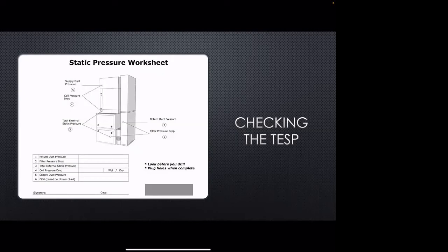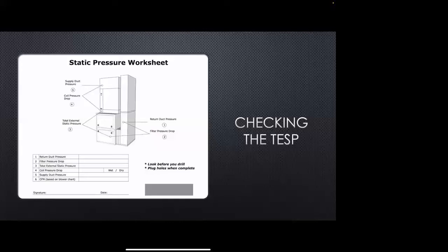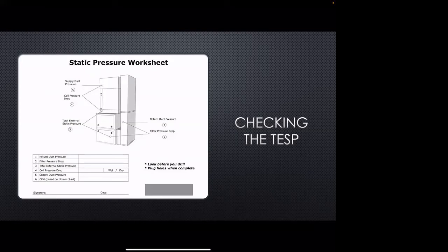Okay. So what they've done to combat that is they started actually putting their pressure drop at a certain CFM on their filter. So it's printed on there. So you can pull out a Honeywell filter, you can pull out a Filtrete filter, and there's other manufacturers out there that started printing that data on that filter for us. And you can cross-reference your system CFM by checking your total external static pressure. Okay, or that filter pressure drop.